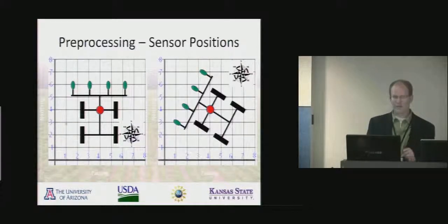So if we want easting, we have to put in a negative value to get west. Negative 2.5 for that sensor for the easting offset, and negative 1 meter for that sensor. Positive looks to me like maybe 0.75, 0.8 meters for that sensor, and it'd be like 2.2 or so for that sensor.